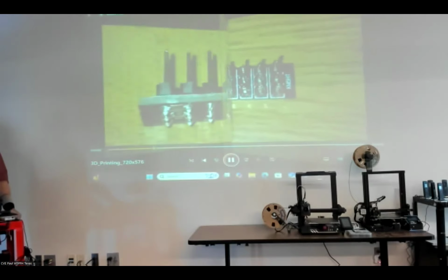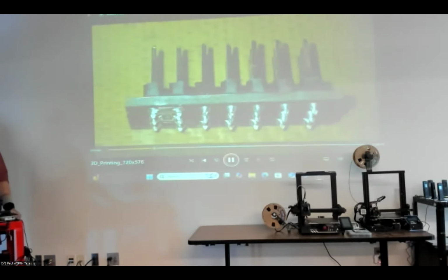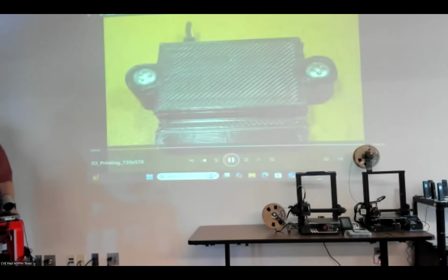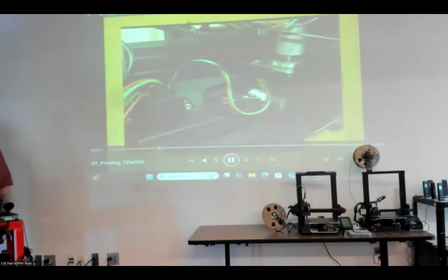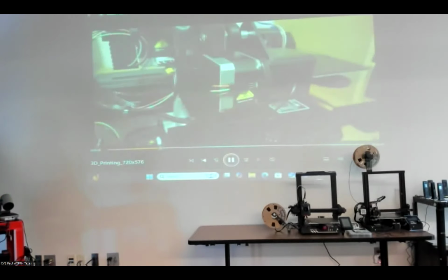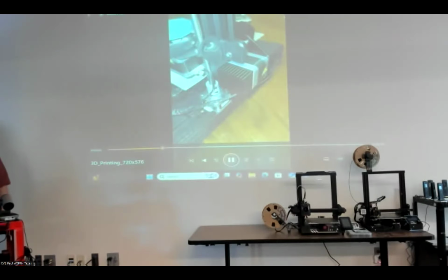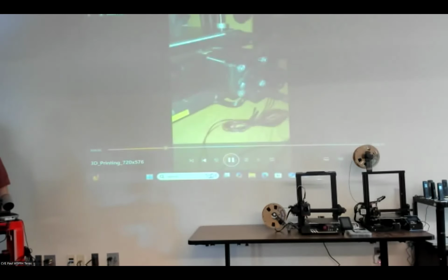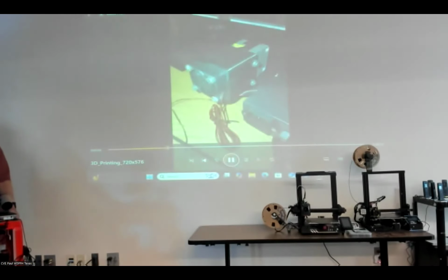You can also do heating element modifications. You can add cameras if you want to do layer videos of your print, where at the end of every layer it takes a still picture, and it builds the print so that after the fact you can go back and do a replay video. That's how you see all these videos on YouTube that are created: a camera snap at the end of every layer that shows the building process. You can add all of those things to a stock Creality printer just by swapping out that firmware and doing a couple of interfaces.